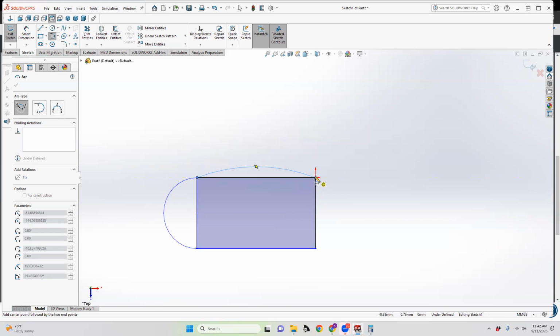So if you start a center point arc, it's helpful to find the center point, which will be denoted on any line with this kind of diagonal double dash. So center point, and this yellow figure will tell you that this is concentric with that point. And then you find, just like the drawing represents, 1, 2 is the start of your arc, and then 3 is where it ends. So you could start your arc out here if you wanted to.